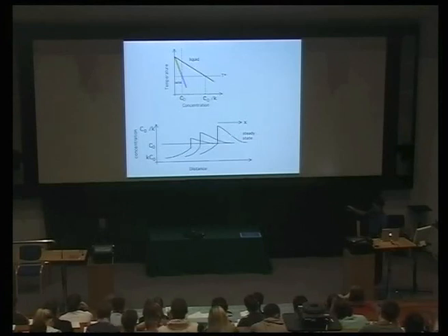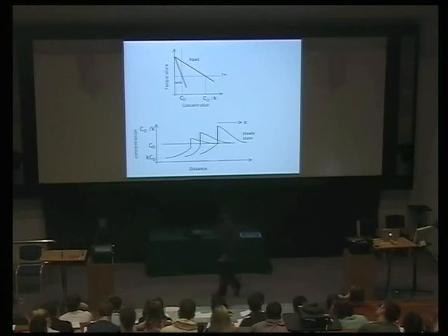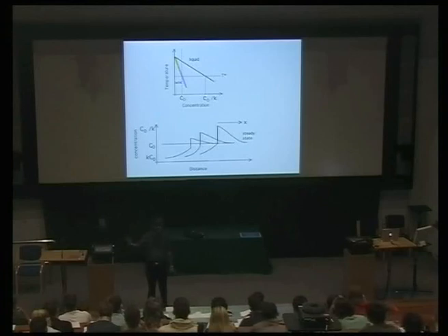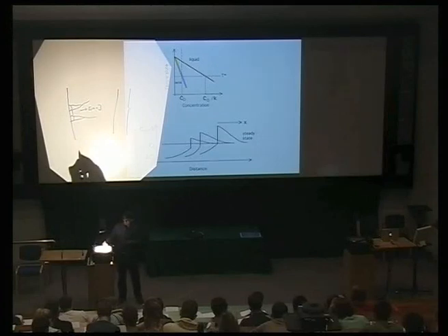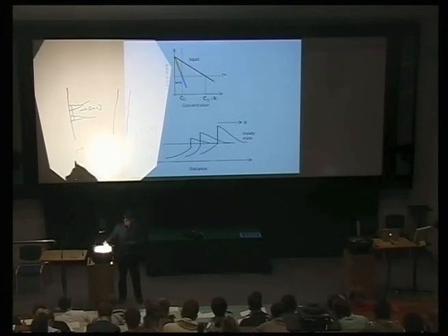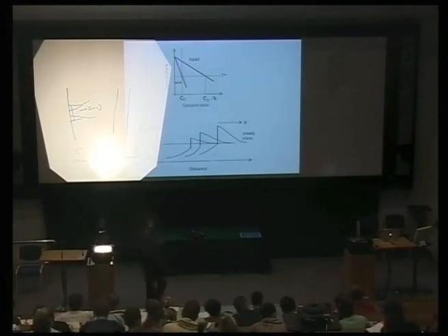And then the amount of solute in the region ahead of the liquid remains constant. And we call this situation steady state solidification, because now, even though there's diffusion happening, it's happening at a constant rate because we are not dumping any more solute into the liquid. So at the point where CSL becomes equal to C naught, we have steady state solidification. So at that point, the interface moves with a constant velocity.